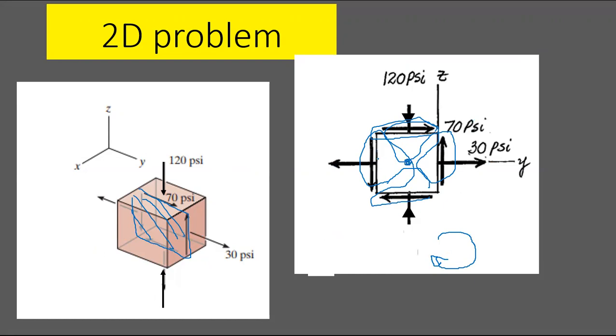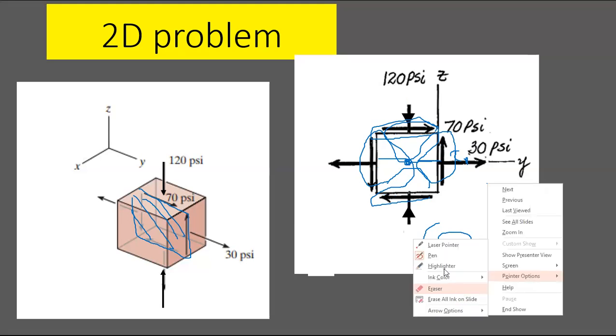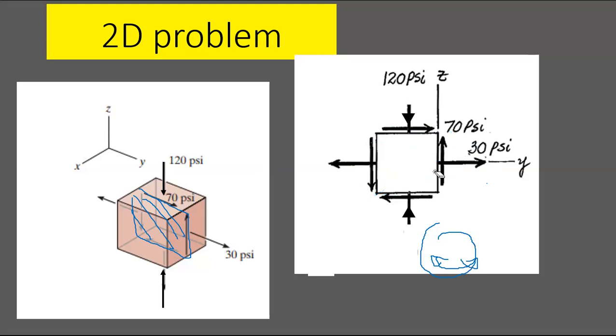You can see the lever arm, so it will make another couple similar to that, so that these shear stresses are equal, because the element should be in equilibrium. That's why we call shear complementary. This is called the complementary shear stress, right? If this is tau x, this is also tau x, right? Otherwise the element cannot be in equilibrium, right? So we usually don't need that to draw the Mohr circle, right?